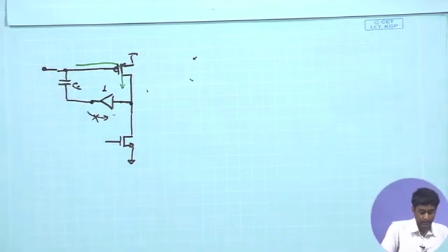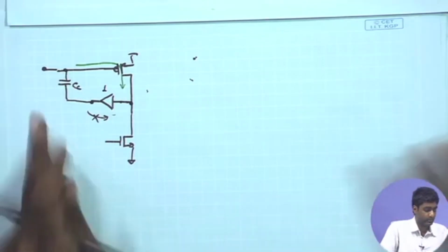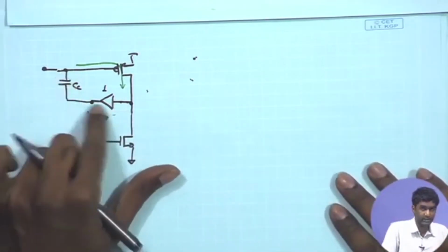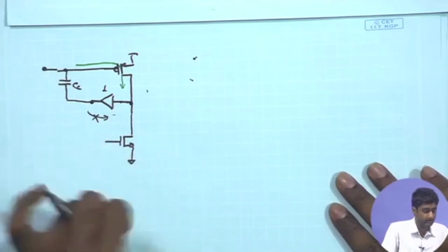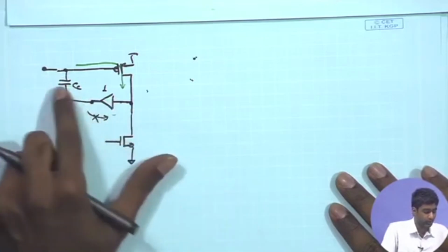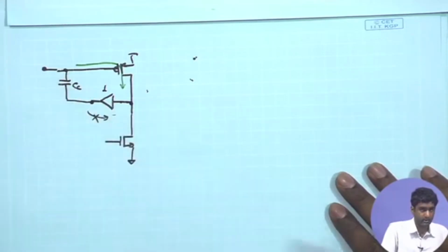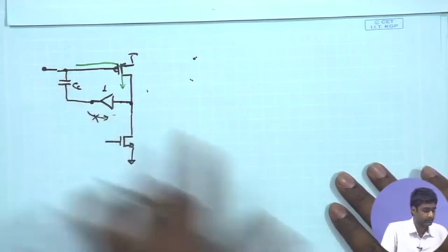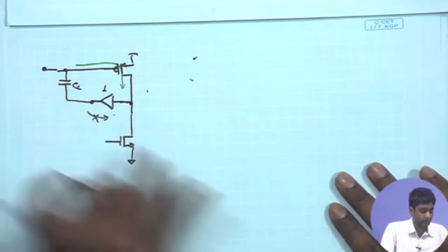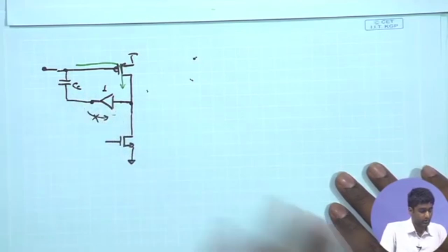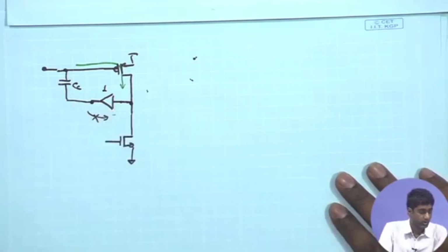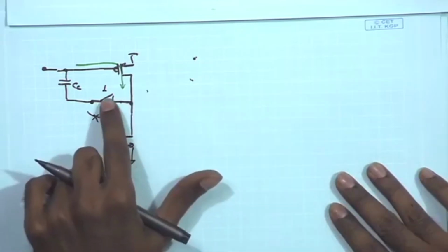Therefore, this is able to compensate the overall two stage response by still exploiting the Miller effect and getting the CC multiplied by a large number. At the same time, it is also blocking the second path and hence helping us in achieving the overall cancellation of the zero.